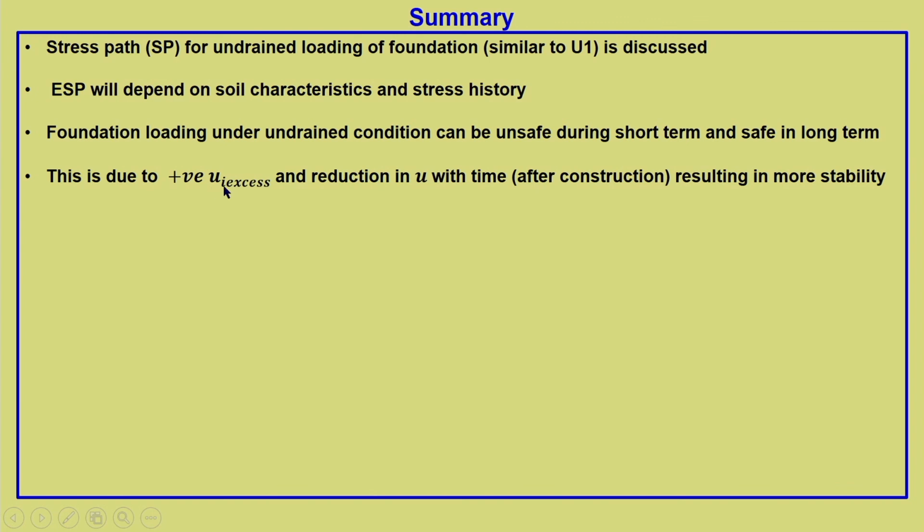This is basically due to the positive pore water pressure that gets developed and the reduction in u with time, that is, after construction, and that results in more stability. But I would like to underline here, it is progressively densifying and hence becoming more stable in terms of stress path. But what is happening to the deformation or the settlement response of the foundation? This densification is at the expense of settlement. So, we also need to look into the serviceability part of the foundation.